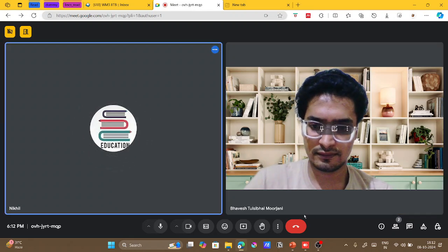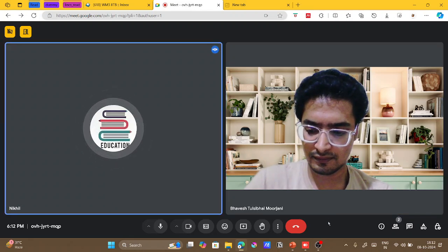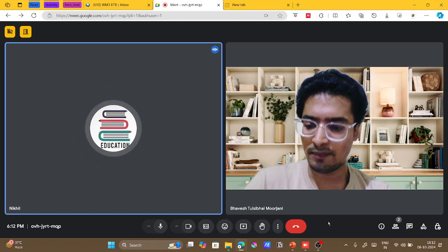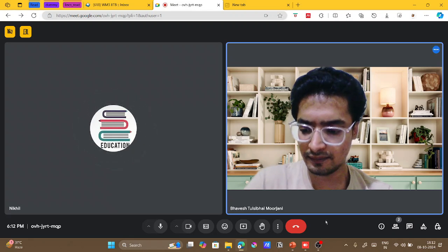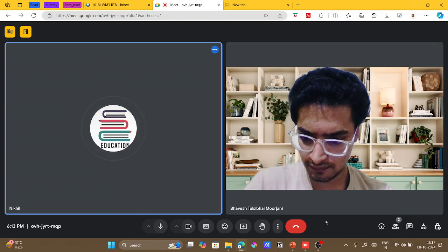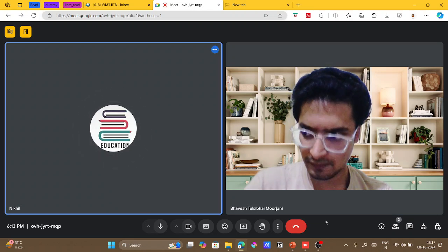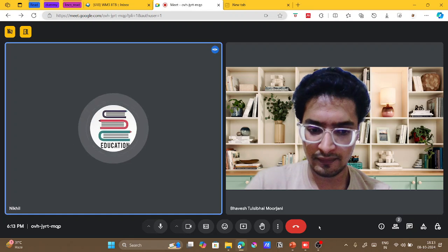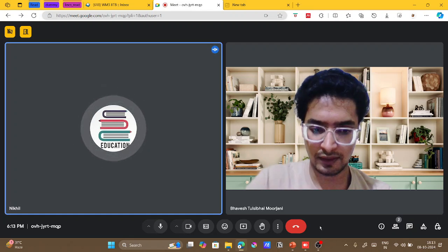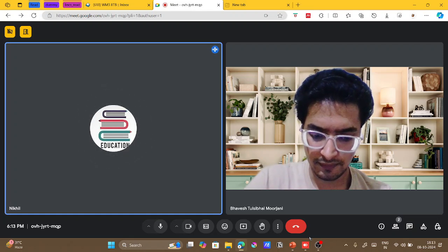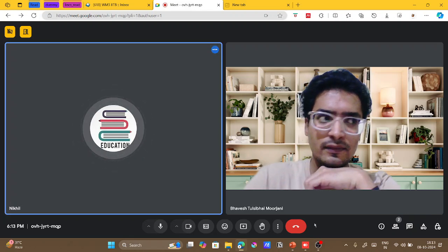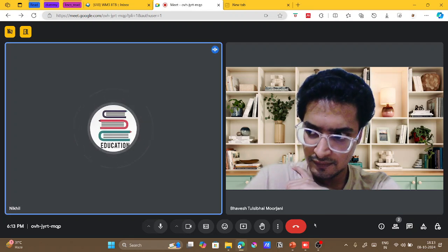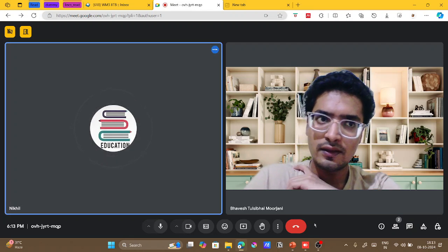By default, Aspen Plus uses steam TA. If you change the default, sir... Sorry, can you repeat, by default what? In the free water method, by default the steam TA method is used. If you go into the property method module, by default it is steam TA, but with SRK, steam NBS is used. So if we use steam TA, the answer is not accurate, so there is some error.